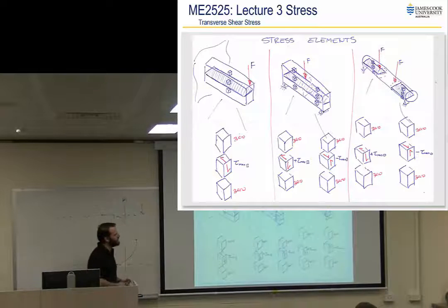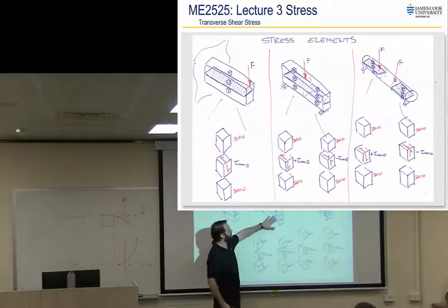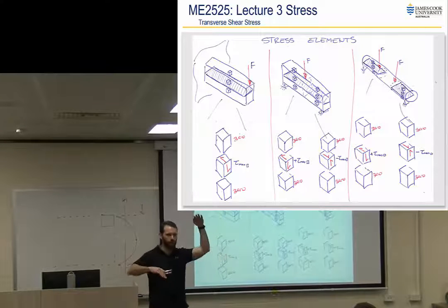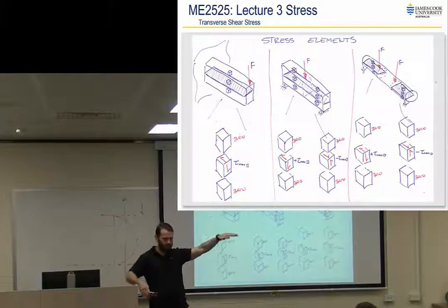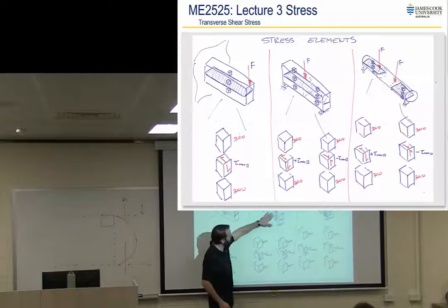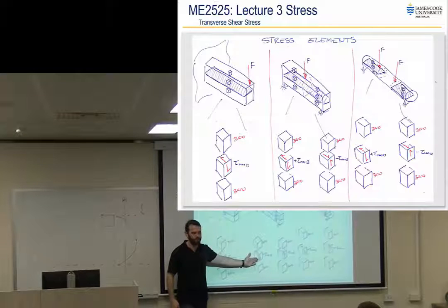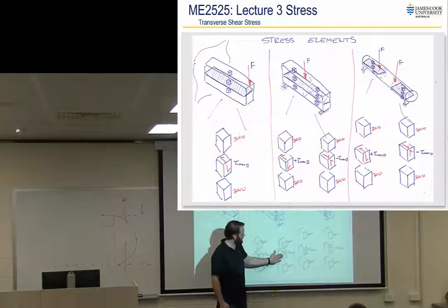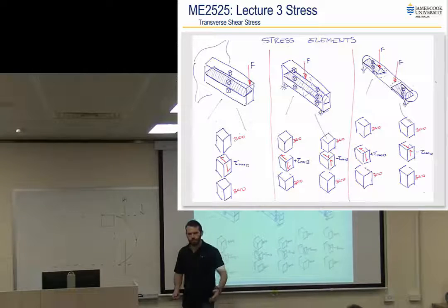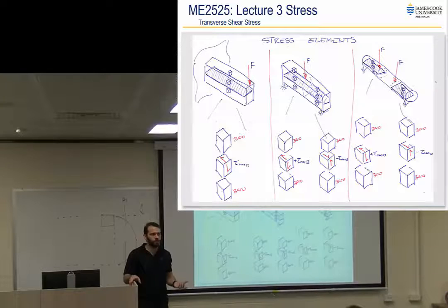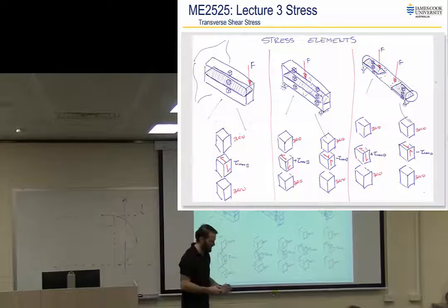Once again, I've got my maximum at that center plane because we know the maximum magnitude is the entire length. The maximum throughout the vertical cross section is at the center plane. So my maximum's anywhere at that center plane. But if I take elements on my left, it's positive shear, down. If I take elements on my right, it's negative shear, up. All right, so if I get the shear force diagrams right, I can use that to get my stress vectors right. I can also use the physical interpretation, like what I was showing you before.